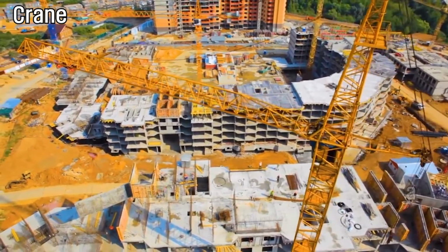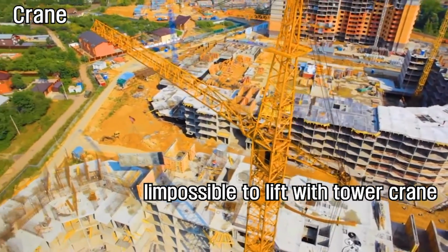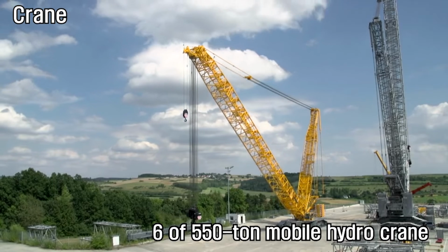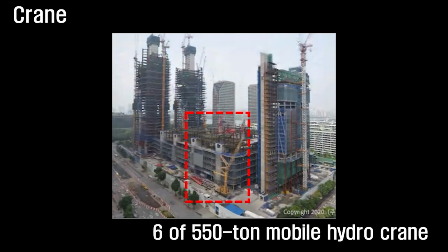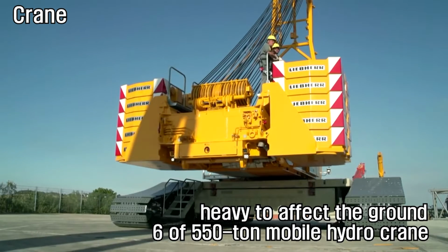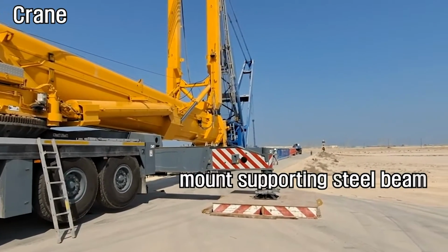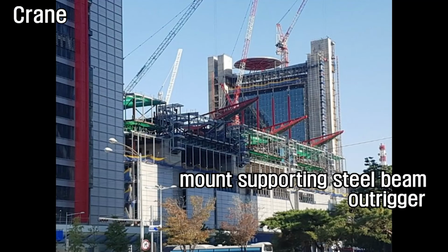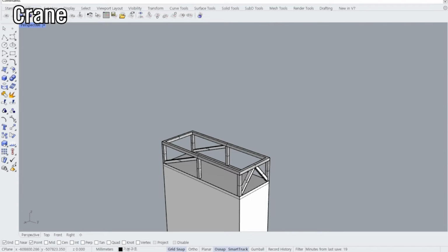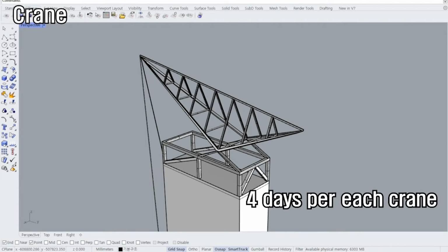As a result, it was impossible to lift with the tower crane that was constructing the existing structures, and thus 6 of 550-ton mobile hydro cranes were installed. The hydro cranes were installed in each location, and they were very heavy, affecting the ground of the building. In order to prevent this influence, the load had to be dispersed by mounting a support steel beam and an outrigger. Meanwhile, the separated segments were installed in the order of torso, leg, front arm, tie beam, and back arm, and it took 4 days per crane.